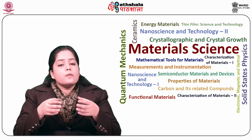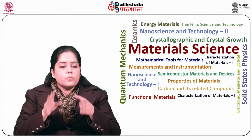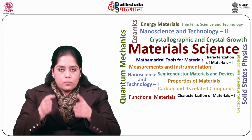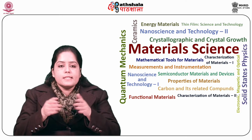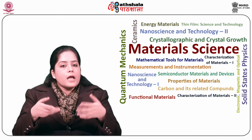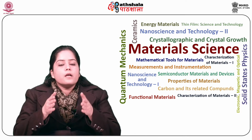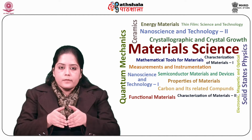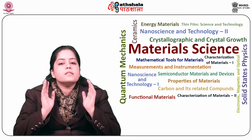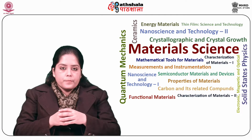Next are SRAM cells, which consist of 4 enhancement mode MOSFETs and 2 depletion mode MOSFETs, the 6T cell. The depletion mode MOSFETs can be replaced by resistors formed in undoped polysilicon to minimize the power consumption and achieve high packing density, the 4T cell.